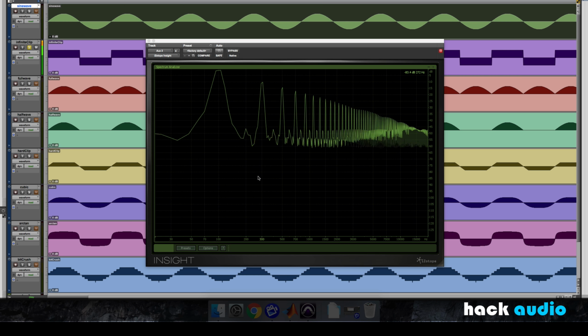Remembering back to what we looked at in MATLAB, this type of function will be described as an odd function. There's this rotational symmetry such that whatever is happening to the positive amplitudes, we have a similar thing happening to the negative amplitudes. So this odd function is going to give us odd harmonics.